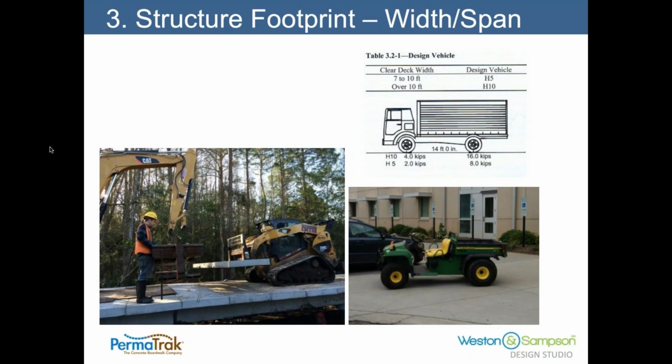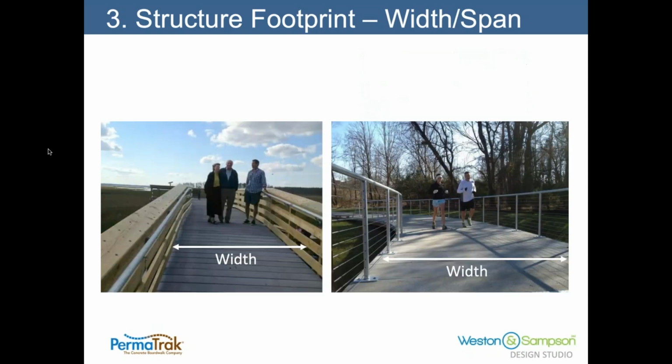If you're designing a metal boardwalk, go to your metal boardwalk designer, your timber boardwalk designer, and ask them, you know, are we building this via top-down construction? Have you considered top-down construction loading? What you see in the picture there is a skid steer. That's probably an 8,000 to 10,000 pound piece of equipment. There's an excavator on the left-hand side. That particular loading put 30,000 pounds of loading on the structure. You have to design for that, simply put.